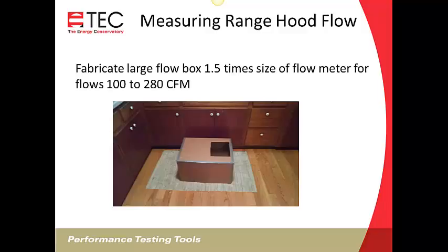You could put a piece of cardboard in the bottom of this box so stuff doesn't fall through the hole, and then you can throw your exhaust fan flow meter and your pressure pan in there, maybe some tubing, and now you've got a box that's usable for carrying things into the house. And it's not just a cardboard box; it's going to get busted up over time. And you could put a gasket on there, so it makes a tight seal against the ceiling when you're taking bath fan flows, and then you've got something that you can also use for kitchen fan flows.